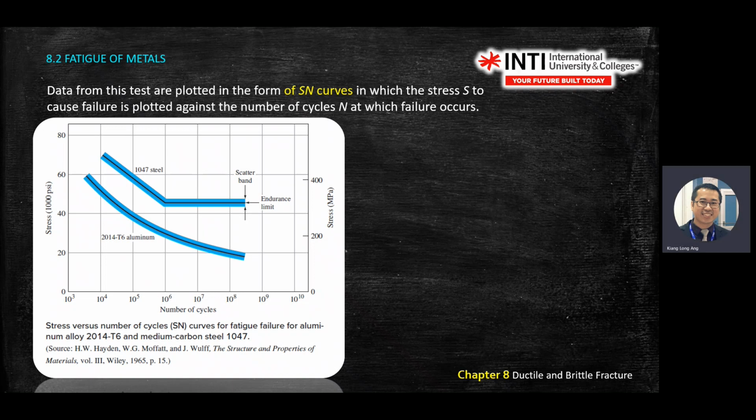So it will fail. So you go to a material handbook or encyclopedia, you find the SN graph. Then you go and find the range 1300 to 1600. There's a line there. You can find something like carbon steel. Then you predict, and then you discuss about the failure stress.